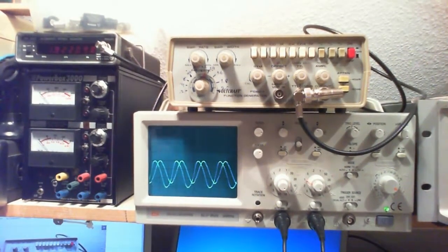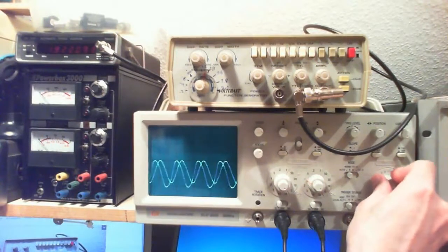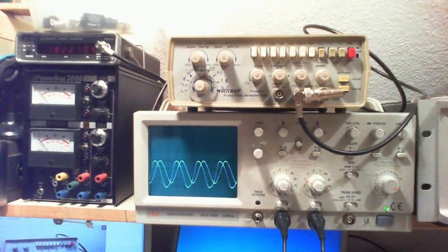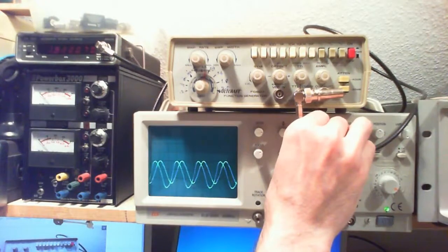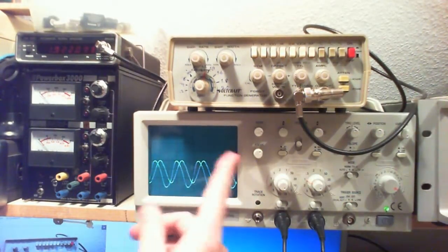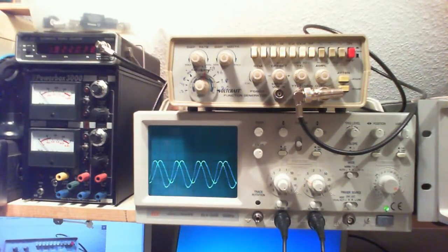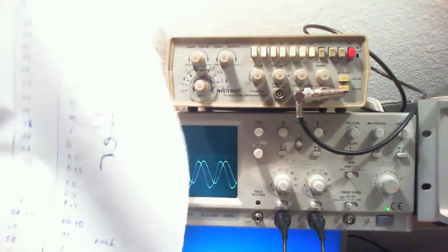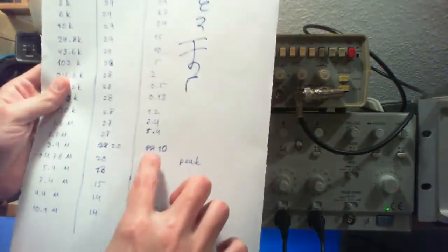and now you can just keep going in this direction in frequency, and I think the phase angle is going to change, meaning that right now the output is leading, so the output will start to lag after somewhere about 4.7 megahertz, where the voltage starts to fall again.